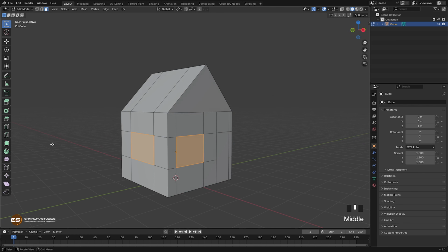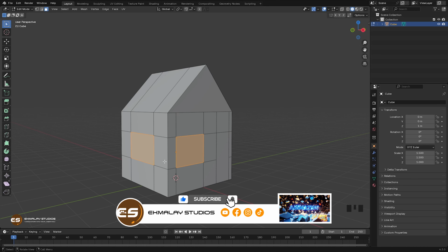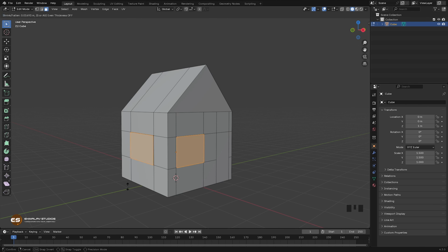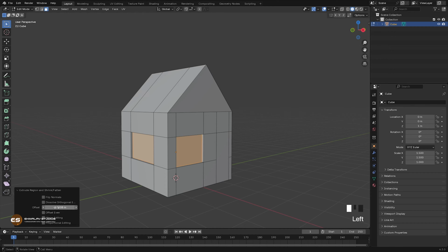And now you can extrude by going to this menu. If you hold down, there are different options, but I'm gonna do it by the shortcut. So if you hold down Alt and E and the second one, just extrude in a little bit like this. If you open this menu, you still have a chance to change the extrude amount you want. So just make sure to put the right one you want. When you click away, you can't see this menu again.